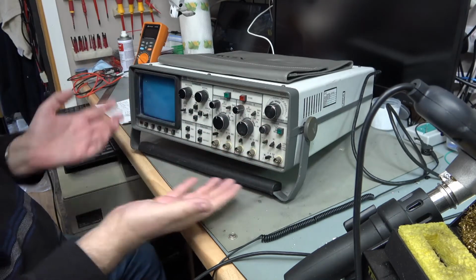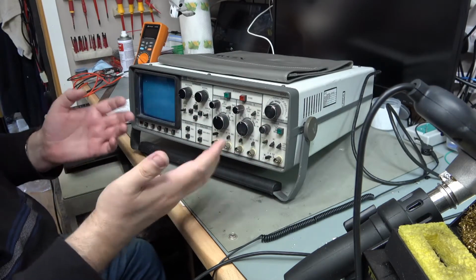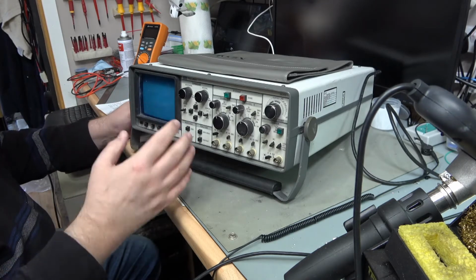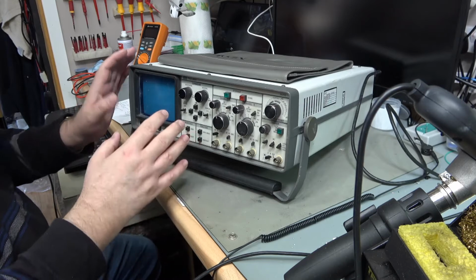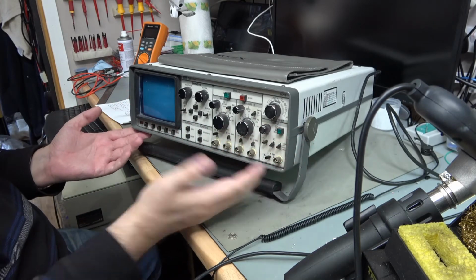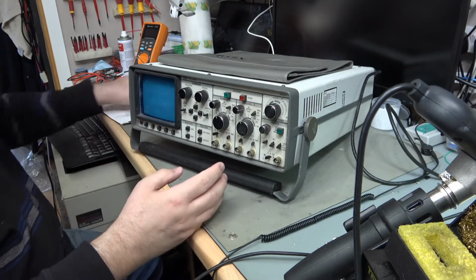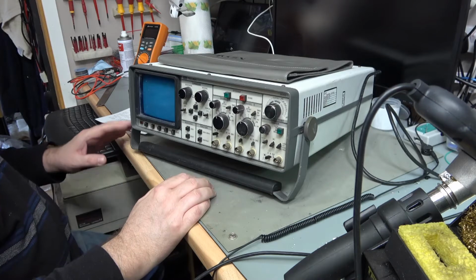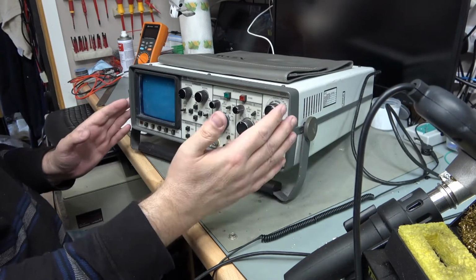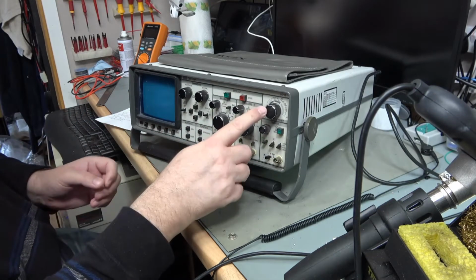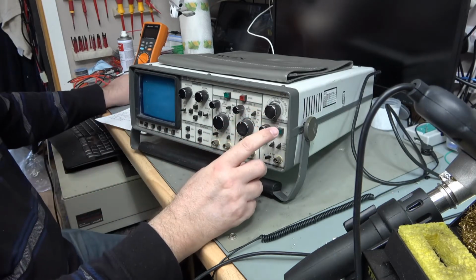What is this? Well, it looks like an oscilloscope, doesn't it? And it's listed as an oscilloscope, but it's a little bit different. I would probably describe this as more a scientific piece of equipment rather than an electronics piece of equipment. It has very limited bandwidth, for example. In the 1 volt to 40 volt range, it's 30 kilohertz. Below that, it's 160 kilohertz. So that's hardly anything.